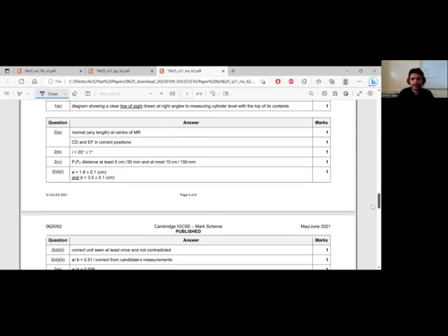And since you are using a meter scale, even if it is like 1.8 centimeter, you are bound to make an error between 1.9 and 1.7. The reason being, let's say you want to find the length of this using a meter scale. Okay. And let's say this end stays somewhere between this particular line and this particular line. Either you have to approximate it to the previous value or the next value as per your best judgment.